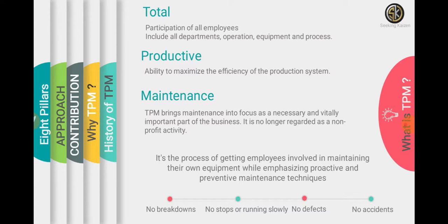Okay, so we need to understand here why there's a need to do all these activities. Okay, so what's the goal? The goal is to create a production environment free from mechanical breakdowns and technical disturbances by involving everybody in the maintenance duties without heavily relying on mechanics or engineers. So how it works: if the engineer or mechanic or maintenance department is able to train the operators, then for basic minor issues the operator will be able to solve those issues by himself, and the maintenance department or mechanic can simply get involved in critical tasks.